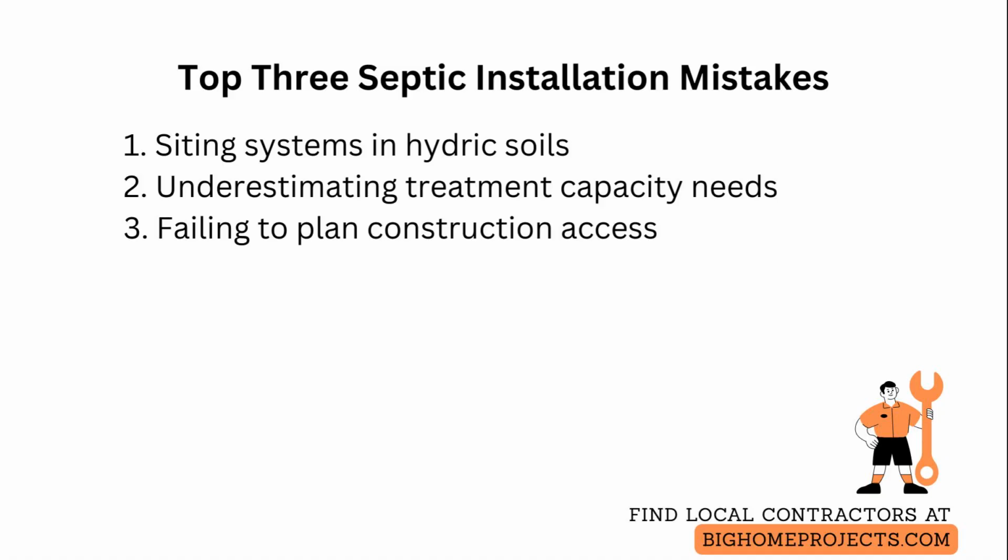Another frequent issue is underestimating treatment needs for a tiny house used seasonally by more occupants than designed for. Size the treatment and polishing elements conservatively and include sampling ports to verify performance.